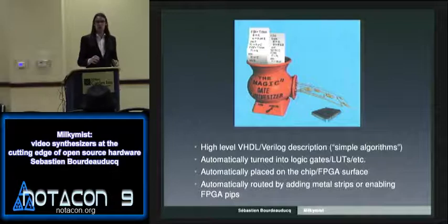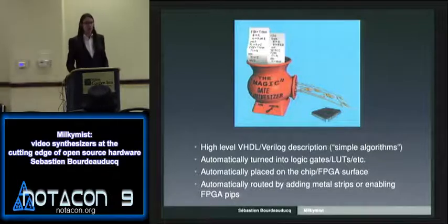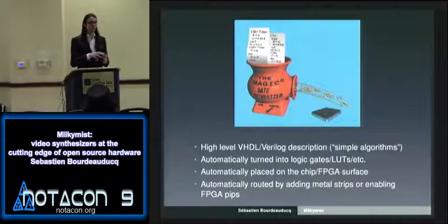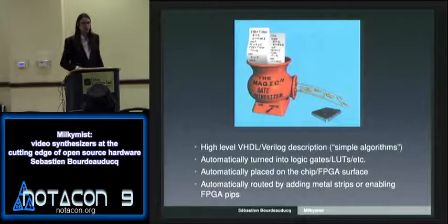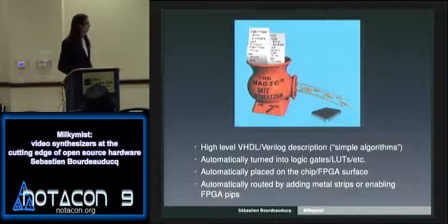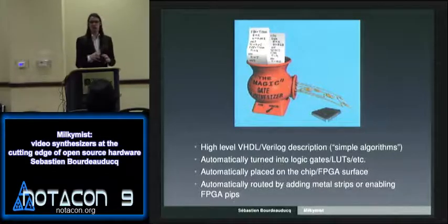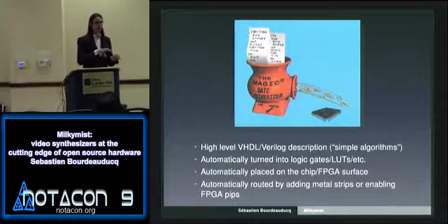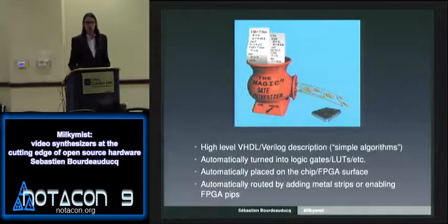But when you are using an FPGA, FPGAs use lookup tables instead of standard cells. So a lookup table is just a black box which can implement any, let's say, 4 or 6 input logic function with one output. And the synthesizer will partition your big logic design into smaller lookup tables, which can later be programmed into an FPGA.